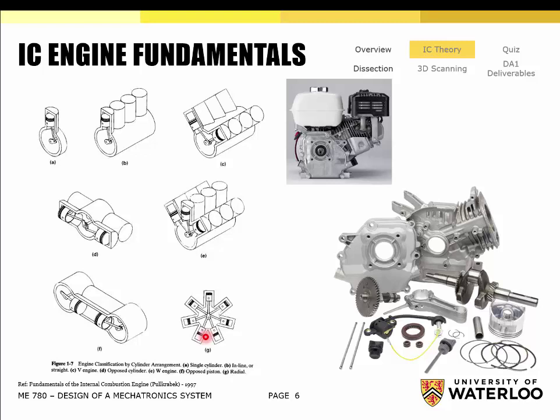Okay. So he's saying it allows it to move forward very easily, and that is true, but maybe what he's trying to say is, if you think about a 7-cylinder engine, which is an odd number of cylinders, if you wanted to do a V configuration or an inline configuration, that's quite long, okay? And when you're putting that type of engine on an aircraft, it affects the balance forward and aft of the aircraft a lot.